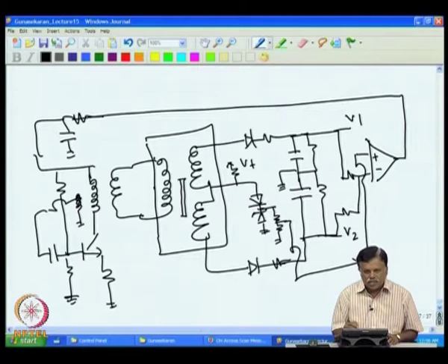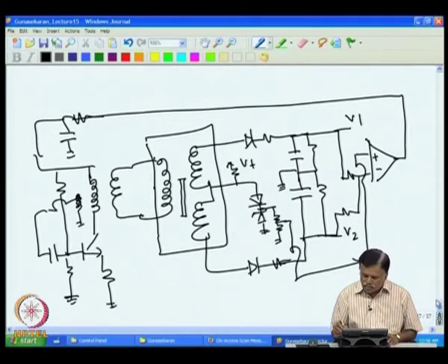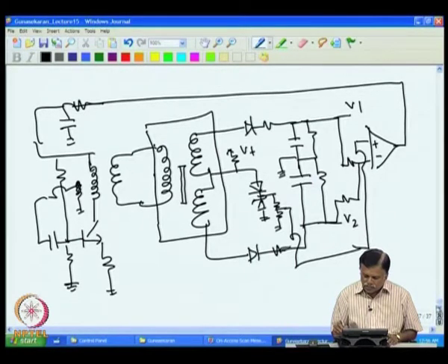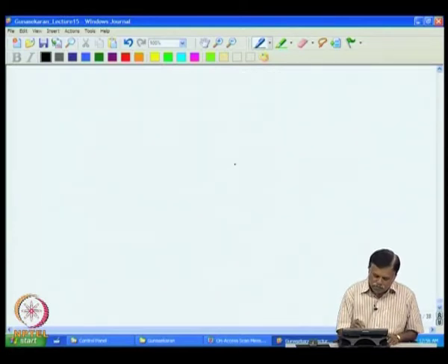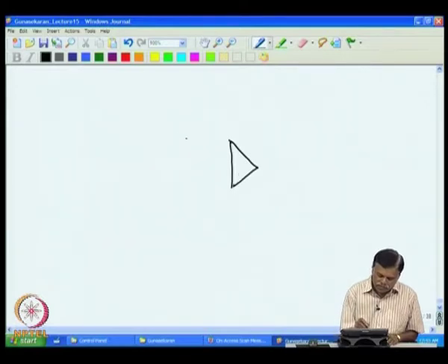So, this is how the LVDT is to be energized first. Now, the V1, V2 can be utilized to produce a current. That can be done by a simple circuit. What we can do is put a current transmitter or convert a voltage into current. For example, if we have this V1 here and V2 here, we can even put a follower.